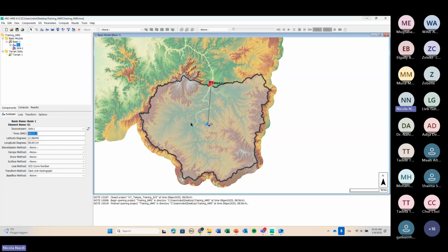And what I mean is, we are in this situation, we have different land use and different infiltration. What we could do is to be more accurate in the creation of the catchments. So we could go back to the identification of the streams, be more accurate by reducing the threshold, and divide this catchment into a lot of different sub-catchments.